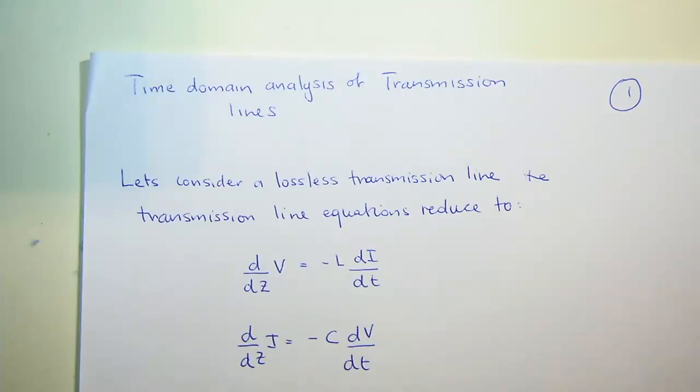What are some of the effects that we would expect to see under those circumstances? Now, you can ask yourself, what are some examples of transmission lines where I'm actually switching on a signal? Can anyone give me some examples? Maybe for the RF guys, you've got a power amplifier, it's switched off, all of a sudden it switches on. It puts a transient on the line, that transient travels down the transmission line, sees a discontinuity, starts coming back.